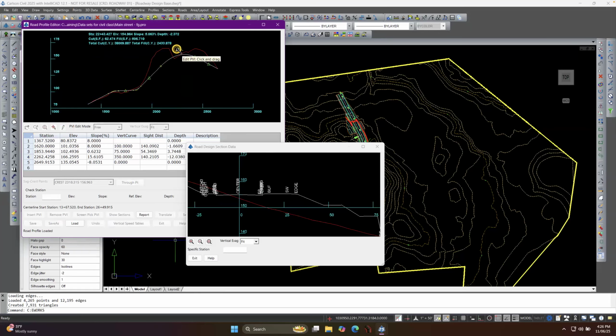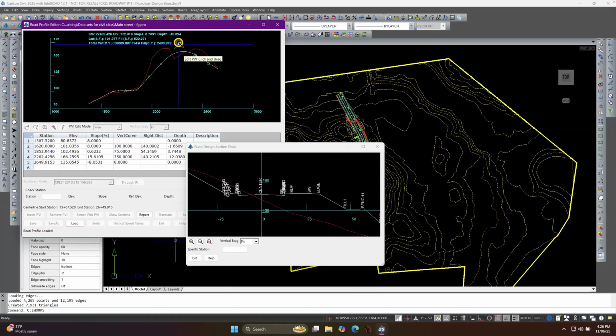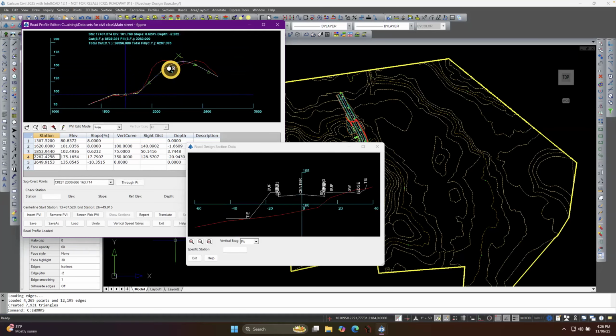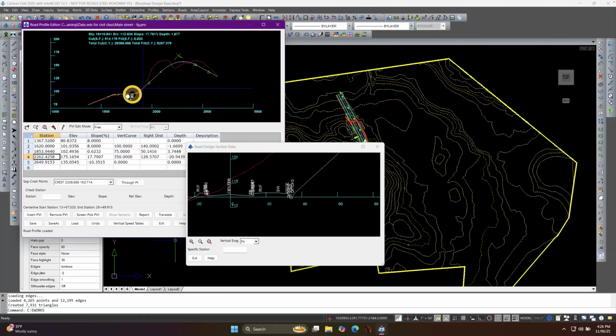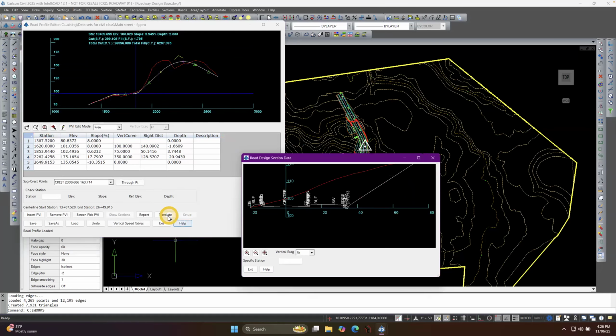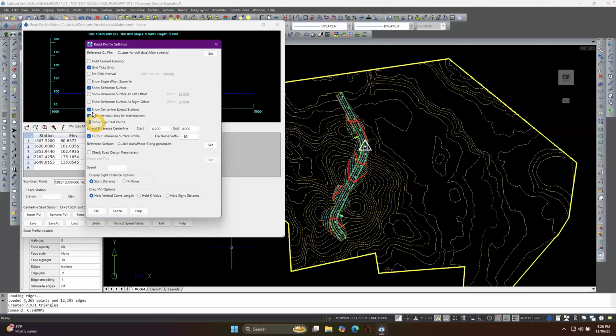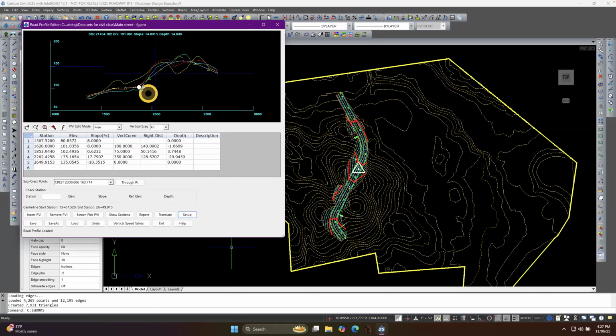So anyway, you can use that to sort of get a sense of it. If you just do it visually, trying to get the center line along the center of the existing road, you see how it's deceptive because I've got all that side distance information out there that you can see. If we show these offsets, show the existing grounds, let's go out 100 feet either side. And now you can see why you're in so much cut because of this stuff on the high side here.